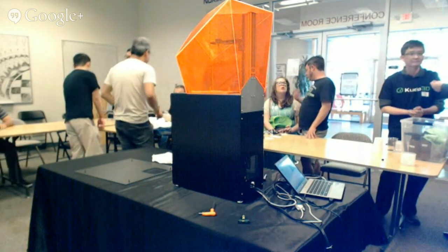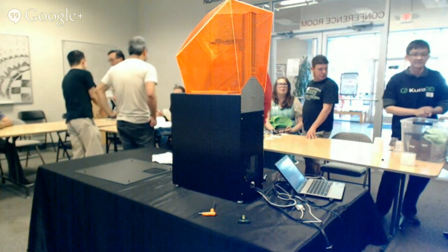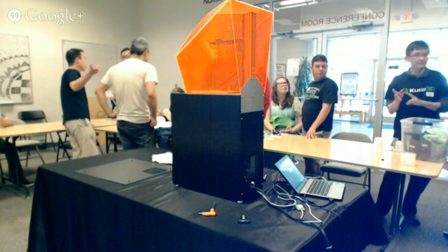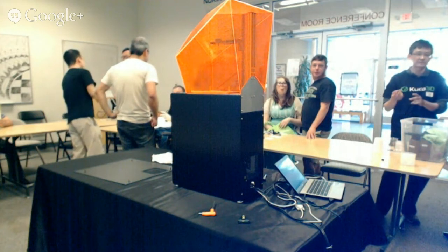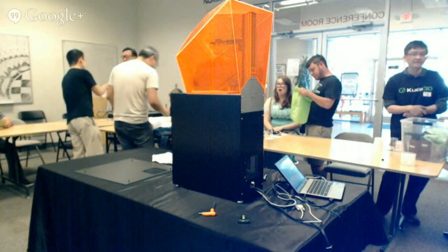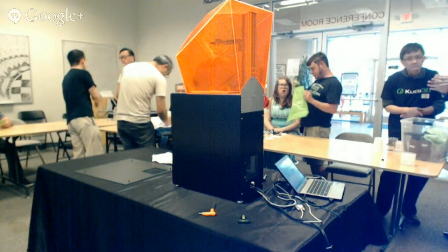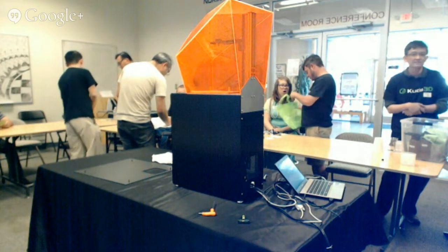It's coming down on the injection nozzle, and there's very little material for that 10 tons of force to get distributed across the whole mold, because this area here is way too thin, right? I can see through it in this part. So this is a design flaw. This part here is too thin, it's not strong enough. So I've got to make this mold bigger in order to give it more space to distribute the force.